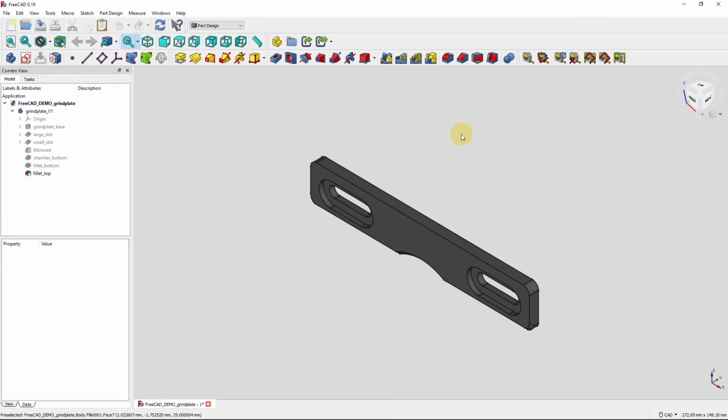The controls in the 3D view are defined here on the bottom right of the screen. If you hover over it, you will see that we have the CAD navigation style that we set up under the settings. Selecting is the left mouse button, zooming is the mouse wheel, rotating is middle and left or middle and right mouse button, and to pan we press the middle mouse button.